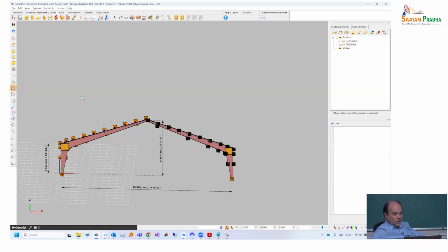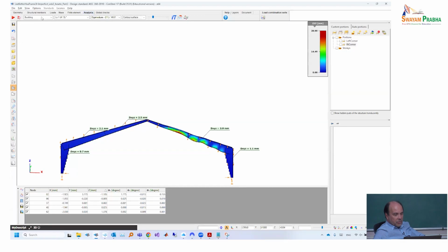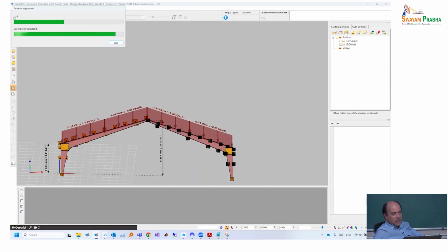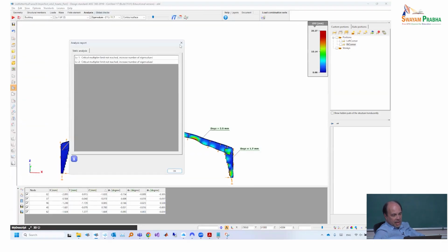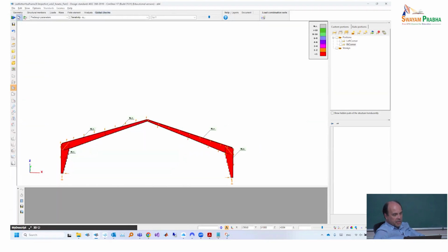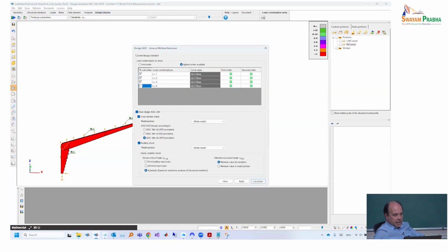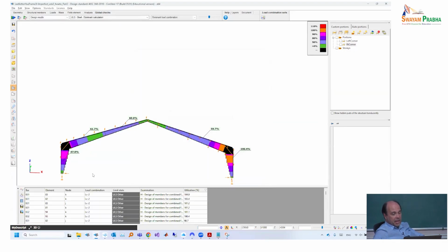Okay, so now when I did this, actually I do nothing more. I just run the calculation. And now this addition will be considered. I still have this message which I explained to you what it means. And now again I select all the other combinations together. I select the automatic, which is already the effect of the buckling sensitivity calculation, and run the calculation again. And the results did not change at all up to now, because again, on the column at least, it's still the web local buckling that is relevant.